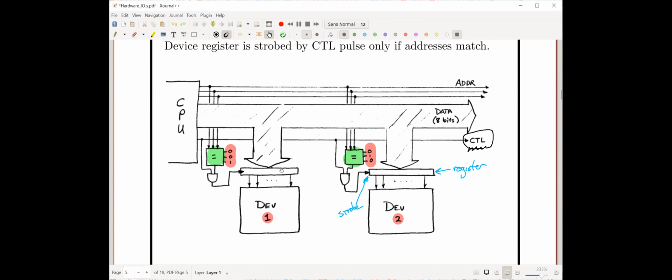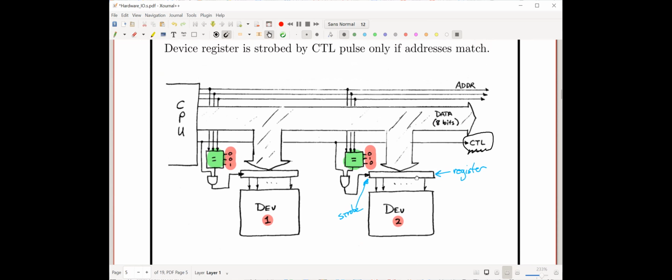Of course, this one does too, and every other device has an output. So how can you hook up two outputs to the same wire? If they agree, that's fine. But what if one's trying to make a 0 and the other's trying to make a logic 1? They will have an epic battle and they will fight, and something unpredictable and bad will happen.